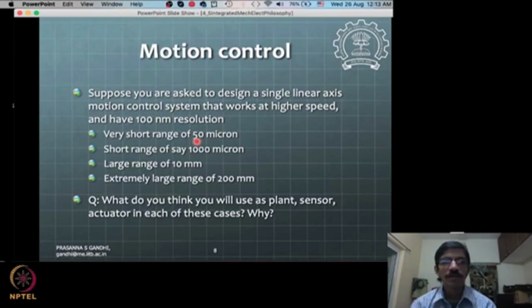Okay, so the voltages are easily in the range of 50 to 100 volts, and given that much voltage, it deforms very little. Okay, based on the different coefficients like d33 and those kinds of piezo coefficients. So if that small deformation comes with a very high voltage, one can see that if I apply millivolts, the deformation will be much smaller, to some few nanometers of accuracy. So from that perspective, piezos can produce very small motions very robustly and very easily.